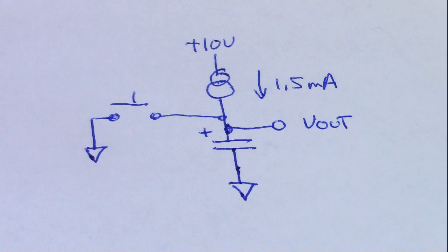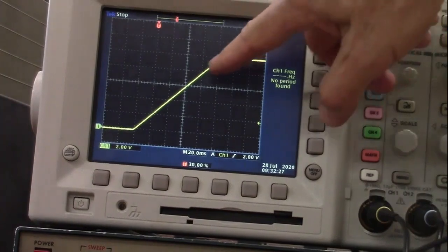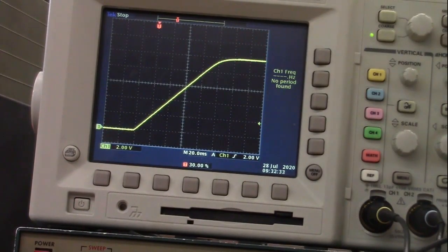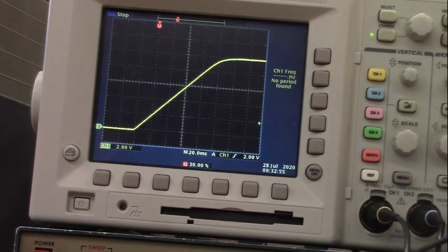And what's happening is, as the voltage across the capacitor increases, the voltage at the current source is decreasing, and at some point, the current source just stops acting as a constant current source. Obviously once we get to 10 volts, there's no way the current source could continue to pump current into the capacitor, because if it did, it would imply that the current source can create current out of nowhere. And indeed, we need at least, it looks to me, about a volt or so across that particular current source. That particular current source is made out of a kind of transistor that needs a volt or so for it to work. So this shows us that I equals C dV/dt.